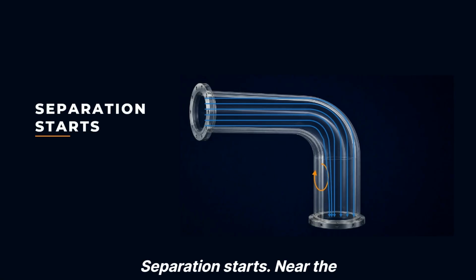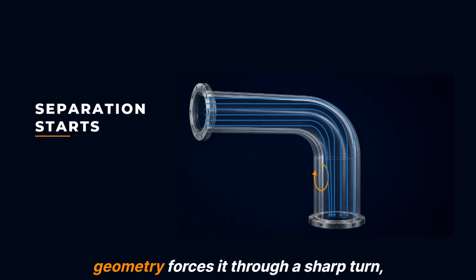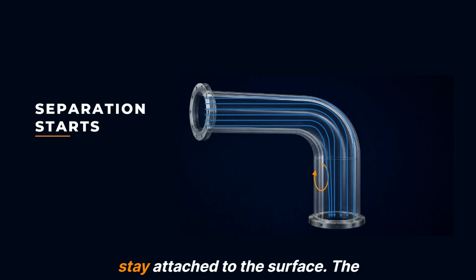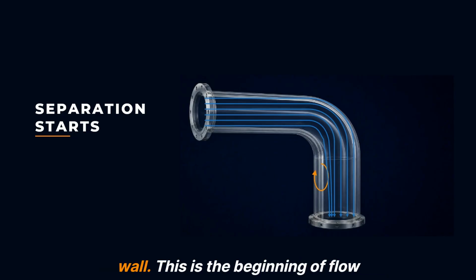Separation starts. Near the wall, the fluid has already lost momentum because of viscosity. If that low momentum fluid encounters an unfavorable pressure change and the geometry forces it through a sharp turn, it may no longer have enough momentum to stay attached to the surface. The streamline begins to lift away from the wall. This is the beginning of flow separation.